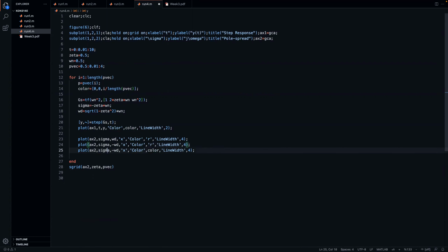And this is exactly at minus p and nothing else. Minus p comma 0, because I'm adding a real pole. I can just add a real pole if it's just a single pole. Now the transfer function is going to be multiplied with p divided by s plus p.